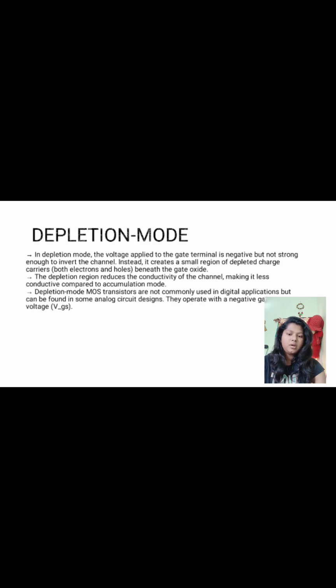In depletion mode, the voltage applied to the gate terminal is negative but not strong enough to invert the channel. Instead, it creates a small region of depleted charge carriers, both electrons and holes, beneath the gate oxide. The depletion region reduces the conductivity of the channel, making it less conductive compared to accumulation mode. Depletion mode MOS transistors are not commonly used in digital applications but can be found in some analog circuit designs. They operate with a negative gate source voltage.